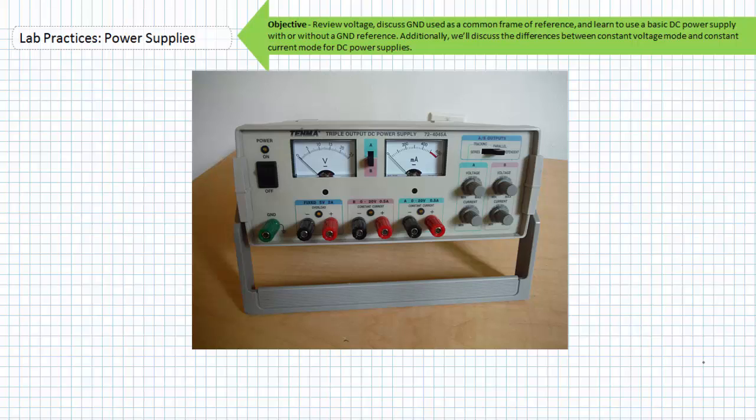Notice there are 2 analog needle meters, one for voltage and one for current. In between them is a selector switch with a pastel green A and a pastel pink B. If I'm using the A terminals and my display selector switch is set to A, I'm really reading the output voltage and current this DC power supply is producing.